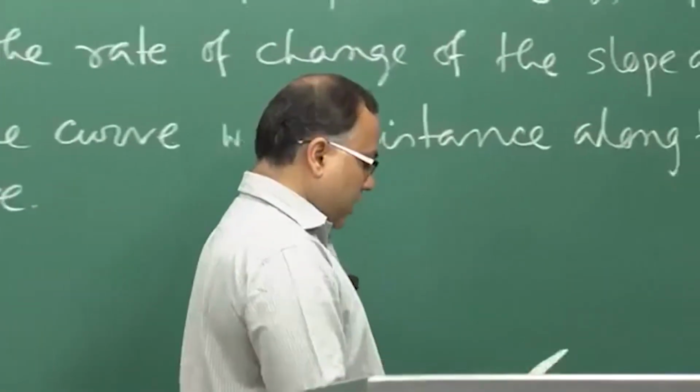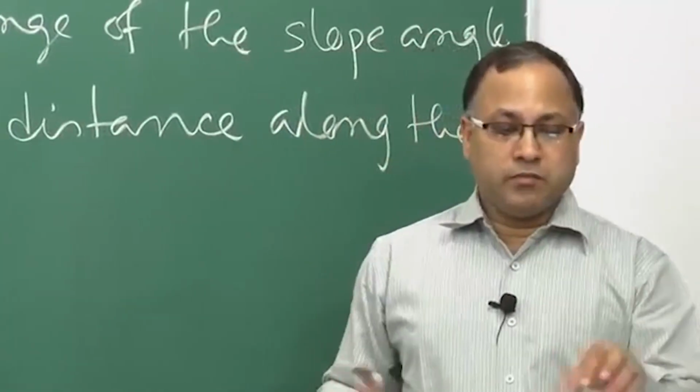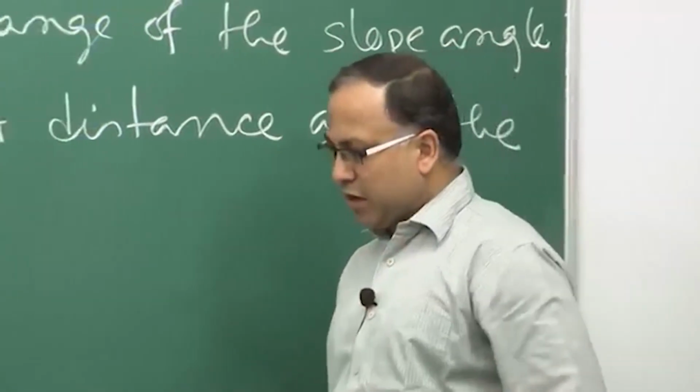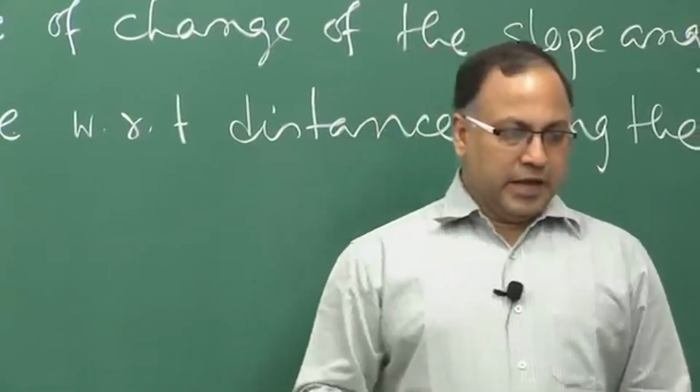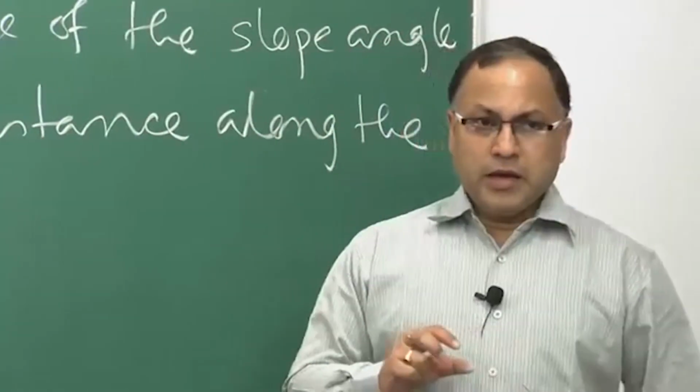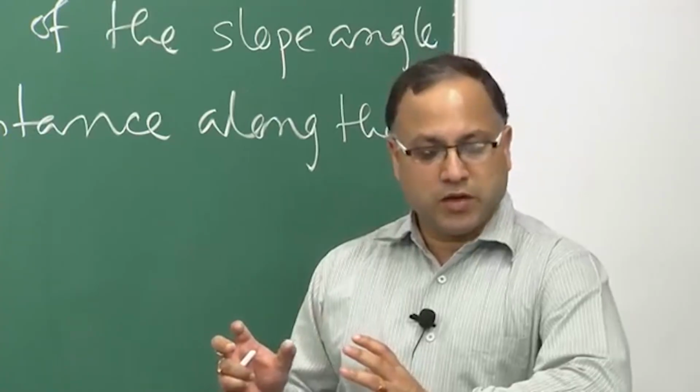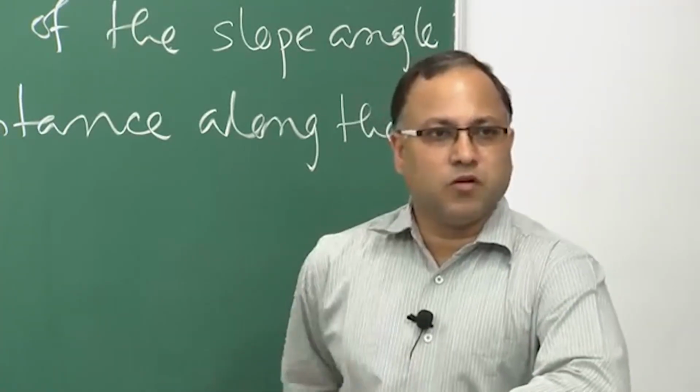Now it can be proved, by following the symmetry argument, that in pure bending, in a plane of symmetry, the plane cross sections remain plane even after deformation.